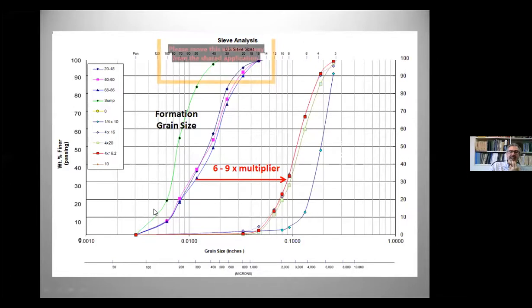In selecting a gravel envelope, we're looking at the overall grain size gradation of the samples themselves, but then textbooks would tell you either pick the D50 or the D30. The diameter of the grain size passing at 50%, or the grain size diameter passing at 30%. And I'll use for this example the D30, and from there I'll choose a multiplier. Again, textbooks will say 4 to 6. You know, if you use the Benison book or even the Roscoe Moss handbook, those will say 4 to 6 times multiplier, say of the D30.